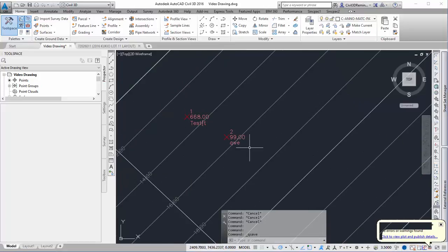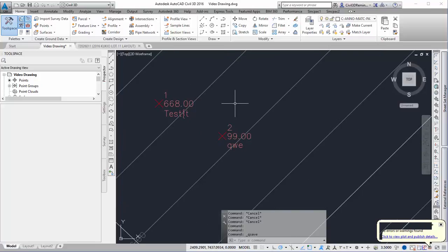All right, so this video covers how we can set the elevation of points when they're in the drawing to 0, but not the actual elevation, but the way we snap to it. So if I were to draw a polyline and snap to this node and move it over and open up